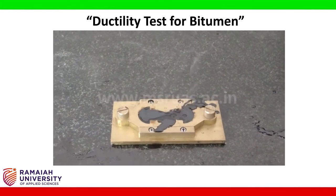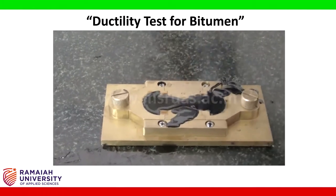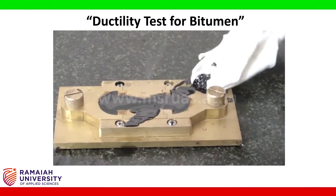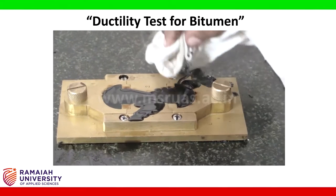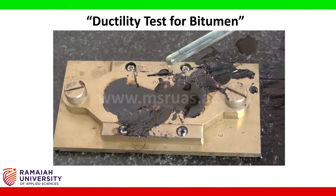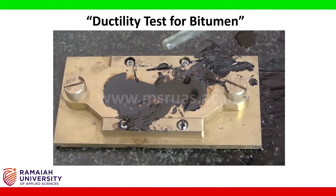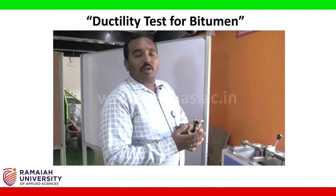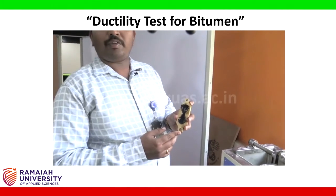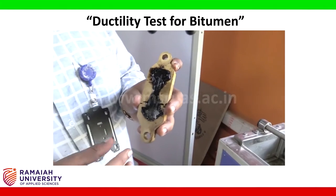After this, we are going to make sure that the excess portion of the bitumen which is on the sides of the mold is removed completely. We keep the prepared sample in air cooling for 1 hour as well as water cooling for 1 more hour. We do the conditioning of the sample. After preparing the sample for ductility, this is the sample we obtained. This will be fixed in the ductility testing machine.